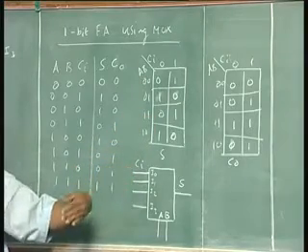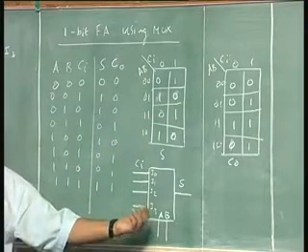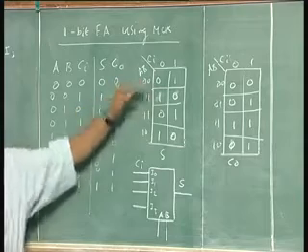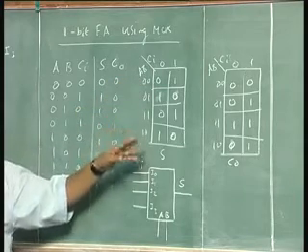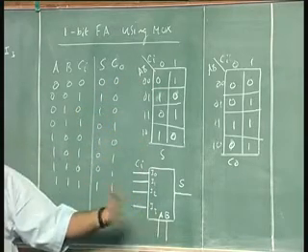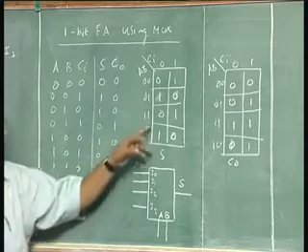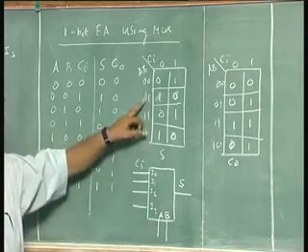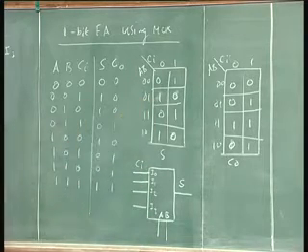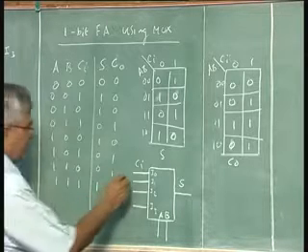But what is so intuitive about it? Because I chose A and B as the selector variables and found out that this is how it has been done. I can also do it some other way. Now, when AB is 0, 1, output will be 1 when Ci is 0 and 0 when Ci is 1. So I need to connect Ci bar.